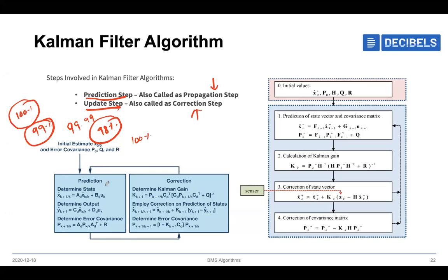And in the first step, before doing all these things, we have to develop some state equations, because Kalman filters mainly use state equations. State equations are the equations that represent how the system is working or how the system is behaving. If you know about state space models, then you might know how to write these state equations.